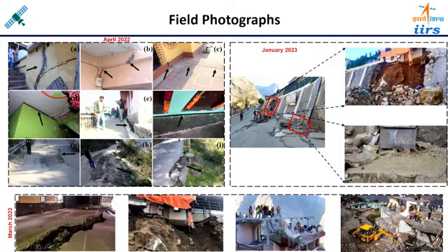So at that time you can see these types of cracks I have observed in the town. And some gaps between the lintel and the walls, and along the roads also some creeping was observed. You can see this creeping, so the land is moving downwards, the road is sinking. Such kinds of deformations were already there in the town.